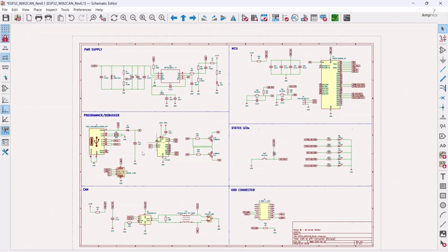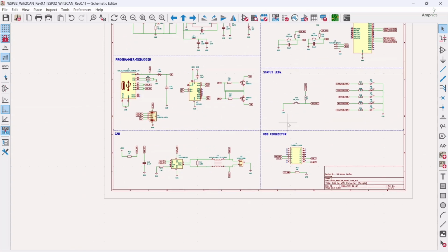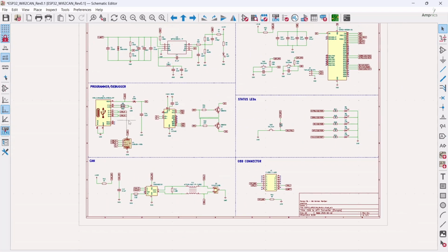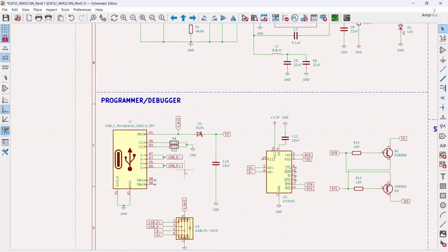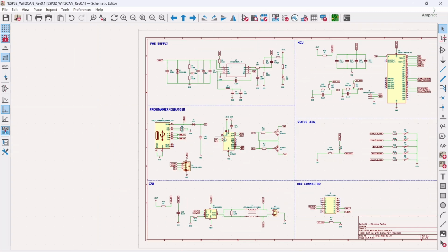Almost our whole circuit is completed, but there's still one thing missing, which I don't think you have figured out so far, but I'm going to tell you here. We have our MCU which works on 3.3 volt, and this device also works on 3.3 volt. We have our 5 volt coming from our type C charger, or type C data cable. So we will get 5 volt data here, while our CH340 works on 3.3 volt. For that, we need to convert this 5 volt into 3.3 volt. So what I will do here, I'll connect this 5 volt to here.